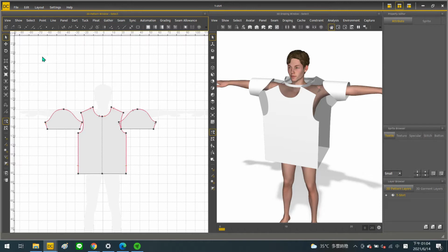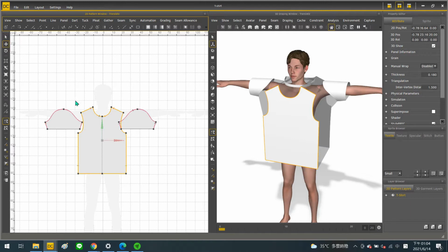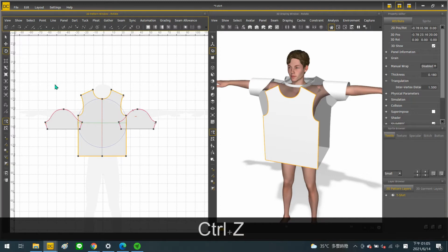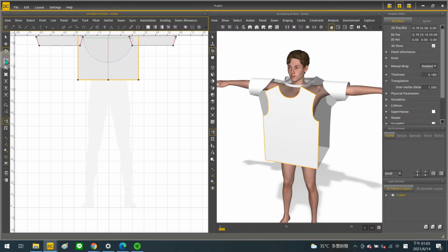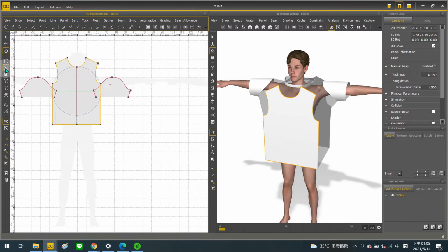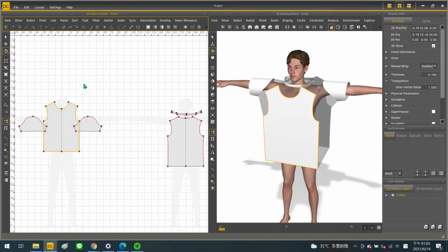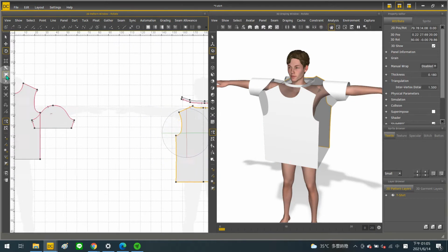On the left of the window, there is a manipulation toolbar. It is recommended to understand this as icons by grouping. The first group is mouse manipulation. You can switch the use of mouse between select, translation, and rotation. The second group is change of view. Restore view is to bring the view to the starting point of the coordinates. And the next 2 are to fit your window to all the patterns or only selected patterns.